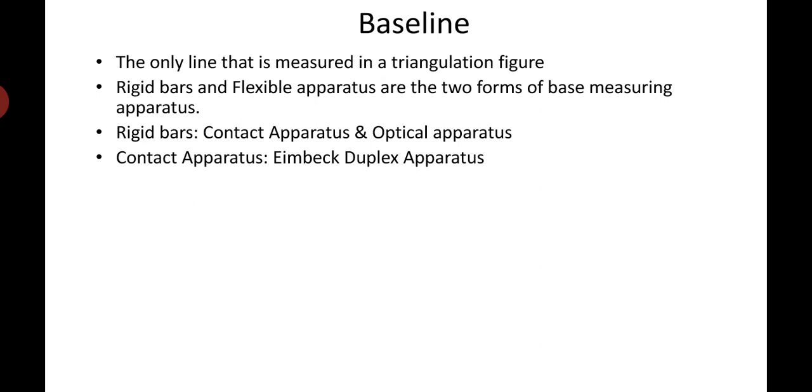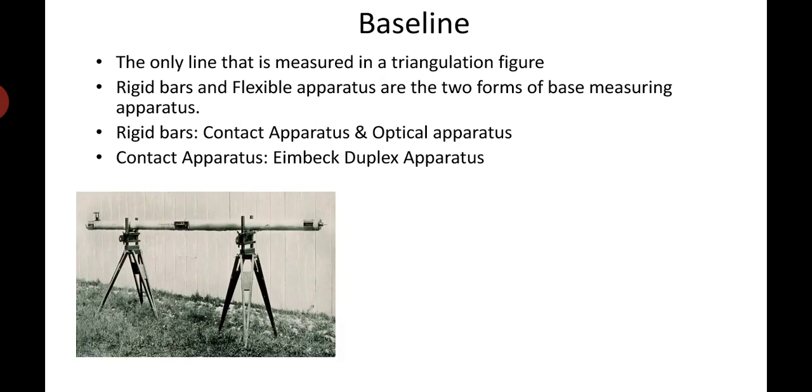The standard length is the ultimate standard to which all modern national standards are referred, in the international meter establishment by the Bureau of International weights and measures. They have decided the various national standards as follows. You can understand the different countries' national standards there. Here I have not written them, but I'll explain that Great Britain's legal unit is the imperial yard, a bronze bar with gold plugs kept at the Board of Trade in London. That is one imperial yard, which is 0.91439180 legal meters.